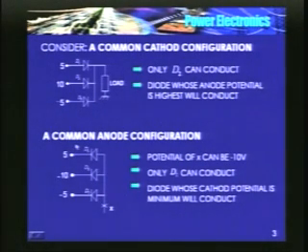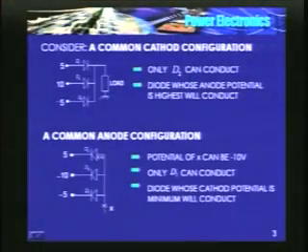What happens in a common anode configuration? I have again a large number of diodes, anodes are tied together, and at the cathodes there are various potentials. I am not going to talk about where this point is connected, let us not worry. Now which diode conducts here? Let us assume that D1 conducts. If D1 conducts, potential of X is 5 volts or maybe 5.7.